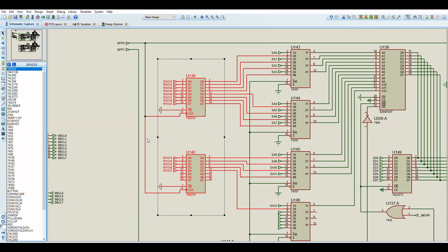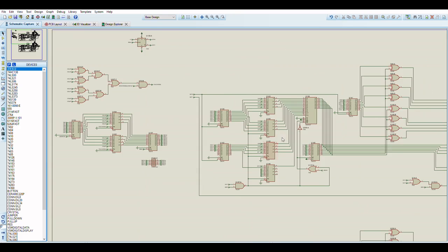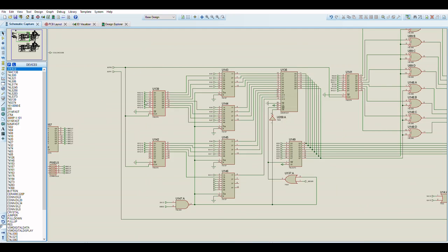Basically, you discard the lower bits that you don't need when you're finally calculating the output, but you still keep on remembering those lower bits in terms of internally accumulating and stuff like that. That's why the adder circuitry on the previous plane is 24 bits, and this is why this is using only 12 bits. So it latches the incoming value, and